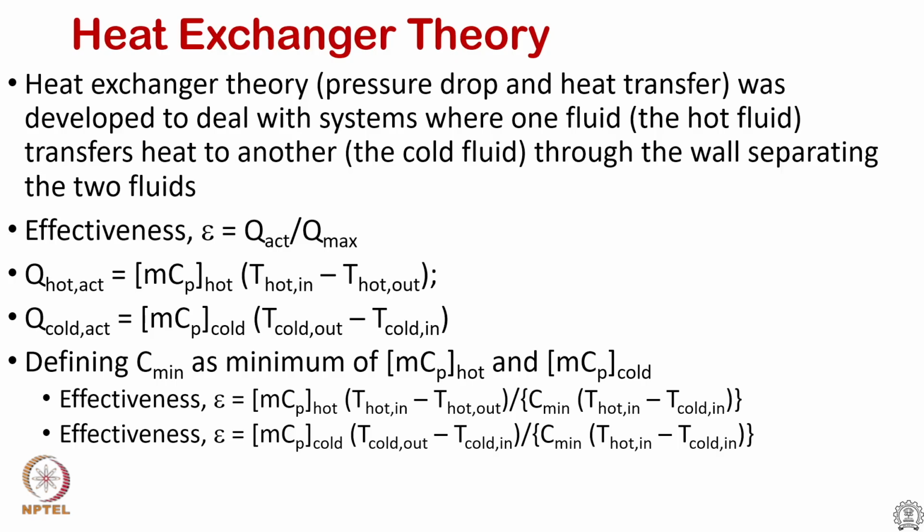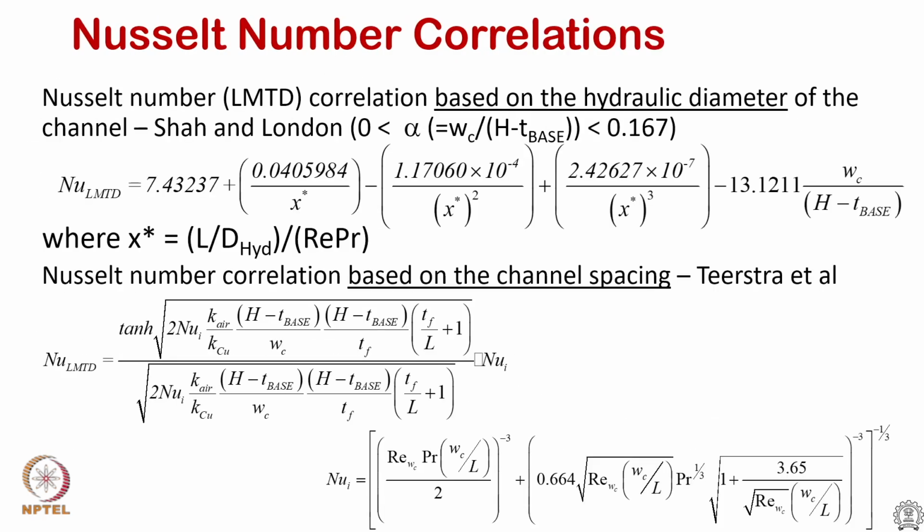With these two things, as a first order approach, we can calculate the pressure drop across the heat sink and the resistance across the heat sink using empirical correlations. This is the first order model one can use to size the initial heat sink, but this is based on empiricism.